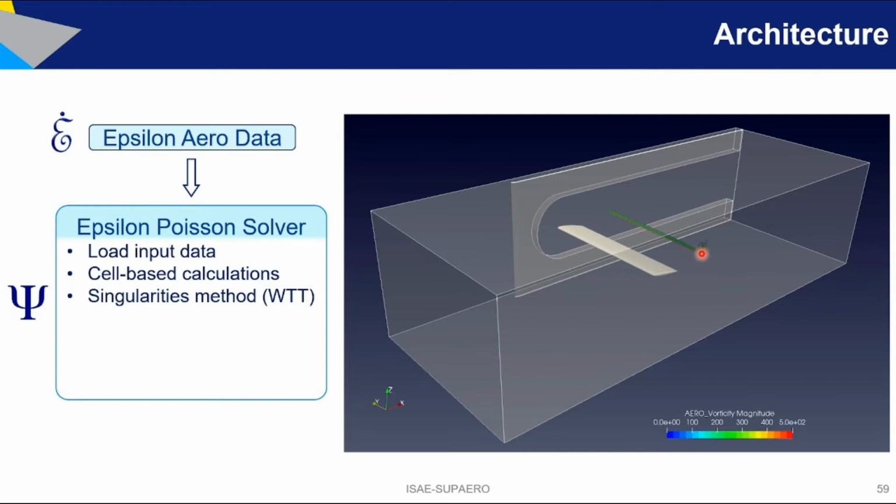This is data that you can gather typically in a wind tunnel, either by PIV or 5-hole probe. And the idea is to generate a panel method at the boundary of the wind tunnel lying at the survey plane position.